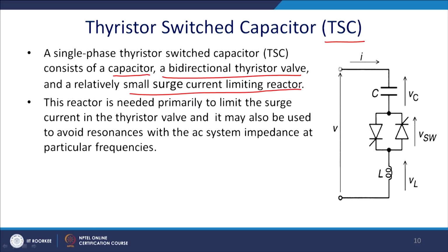So, generally an inductor is required to be placed to block the high inrush of current to the thyristor, and the capacitors will be switched on and switched off, and thus it will deliver VAR in most cases instead of absorbing VAR, and it will control the reactive power in that fashion.